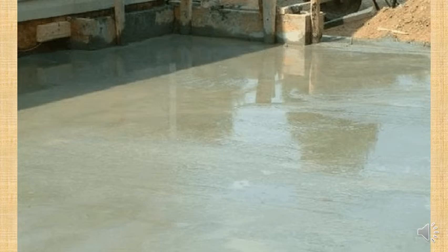That is water bleeding out of the concrete. That's going to weaken the concrete. They've probably added too much water to the concrete mixture, and it's created this bleeding or this minor segregation. So that's another thing we want to avoid.